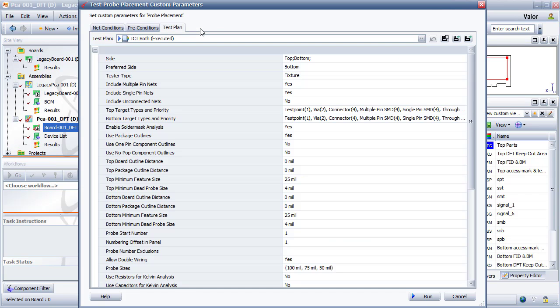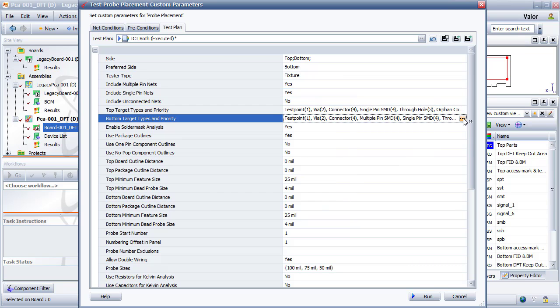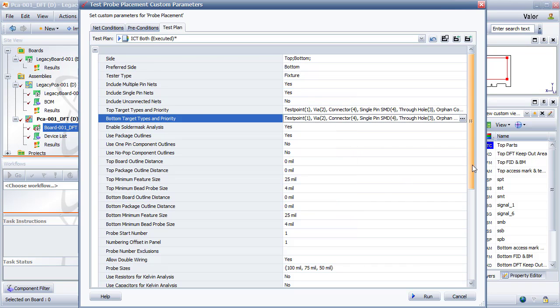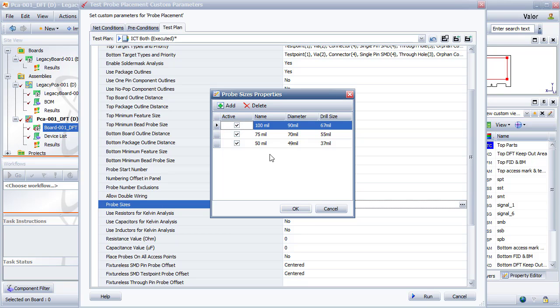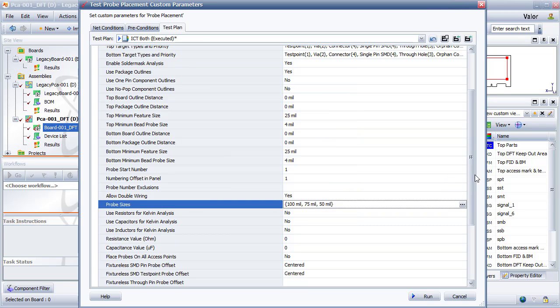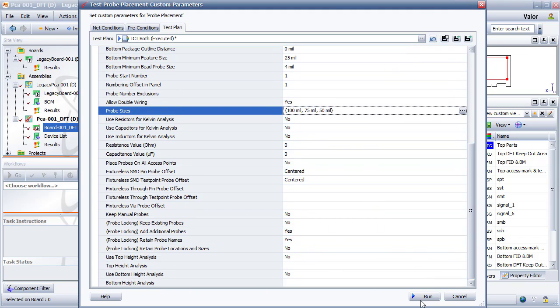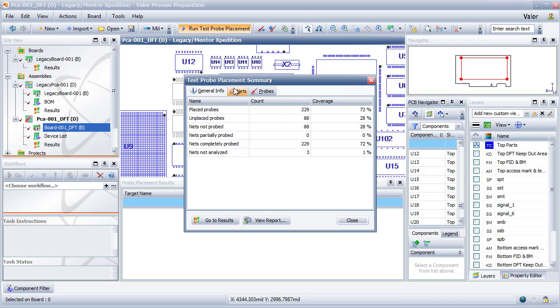Predefined test plans allow an initial assessment on the testability of the design that can then be tuned to maximize the available test locations. The philosophy here is to provide complete data to the analysis engine with user-defined parameters and let the software determine the available access. It shouldn't require significant manual analysis by the test engineer first to create a solution and then tell the software what to do. That approach does not reduce the time and effort on test engineers.